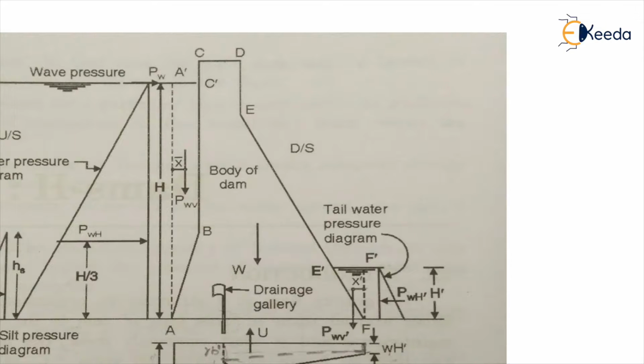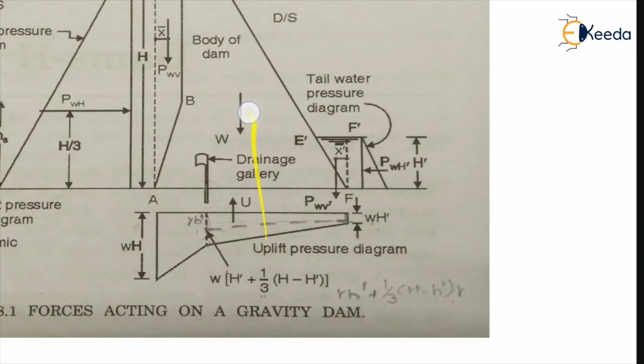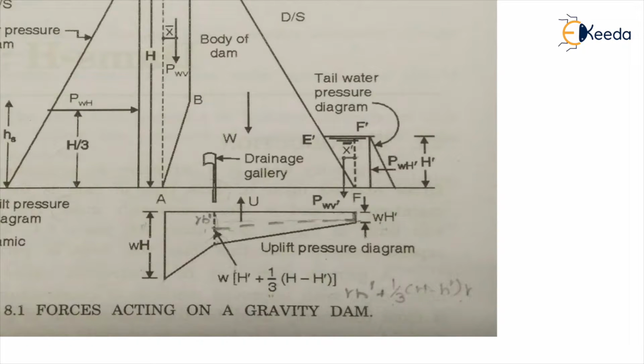Sometimes, through the cracks and pores, water collects and seeps under the base and foundation of the dam, and this water pressure exerts a force on the gravity dam in the upward direction, which is known as uplift pressure or uplift force, from water which seeps through the various cracks, pores and joints.